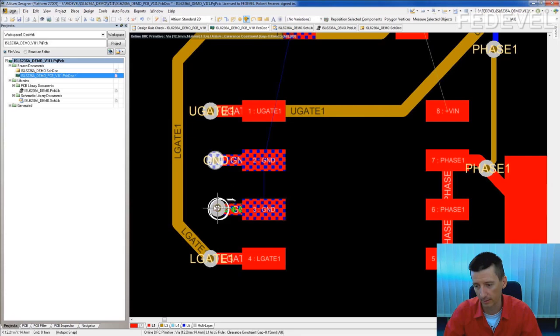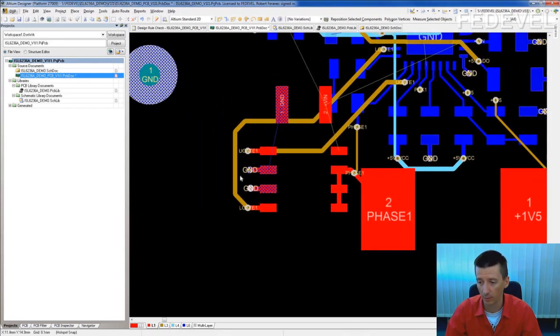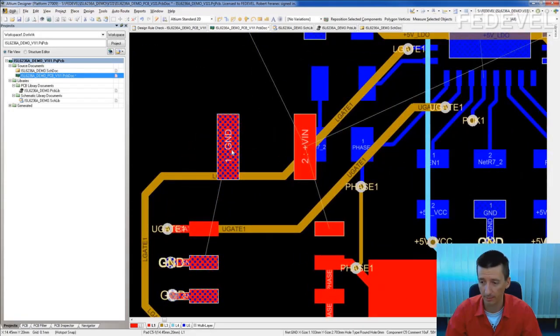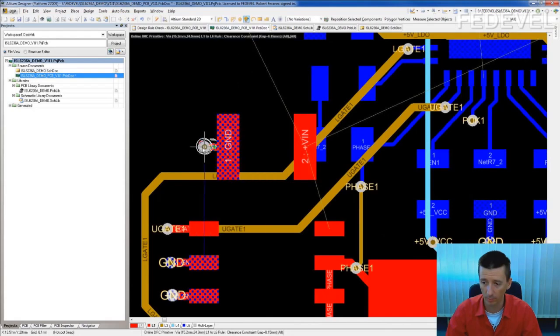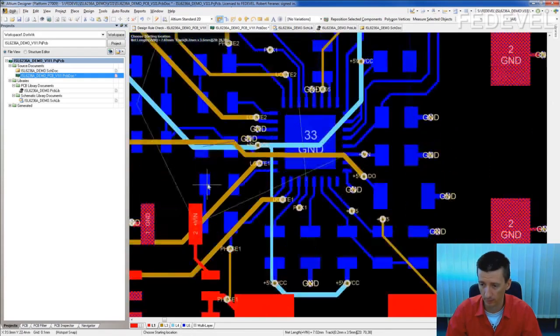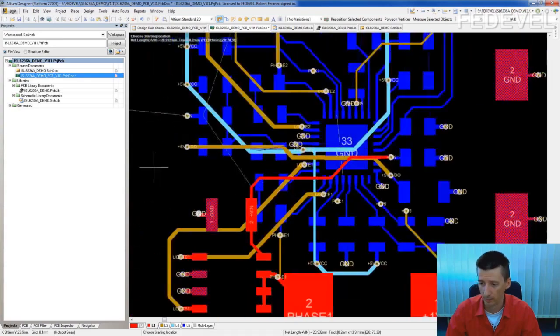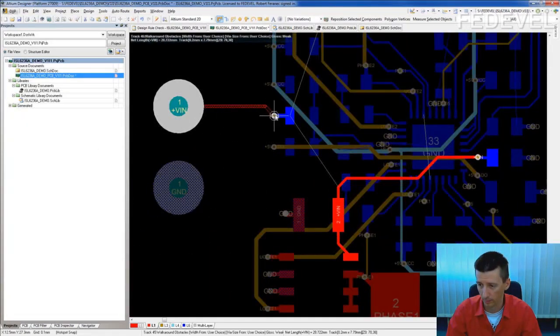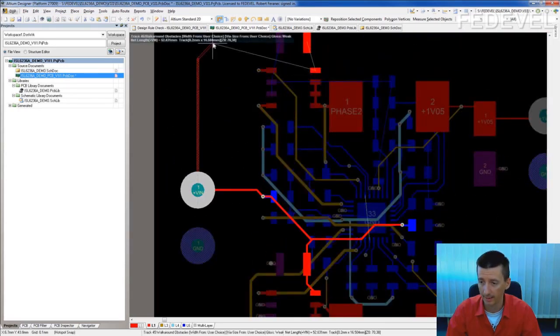Again, these are transistors. Here a big current will be flowing, so we will improve it. Same, here is a capacitor with big current. We will draw small planes everywhere. You need to always think ahead how you use your layers.